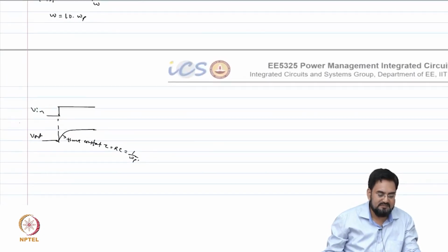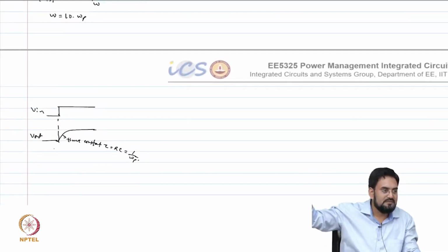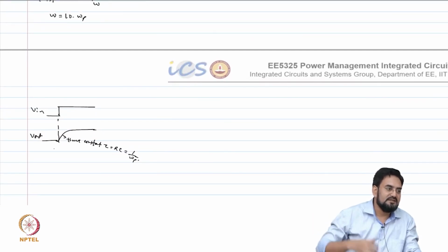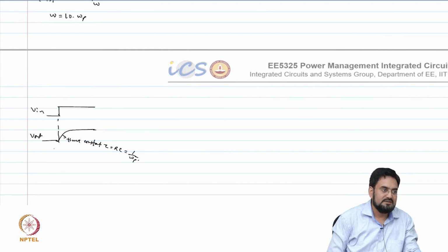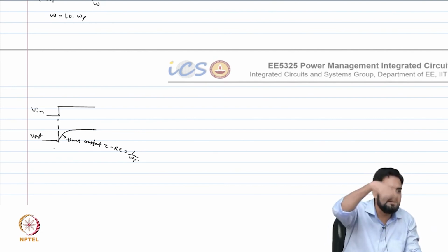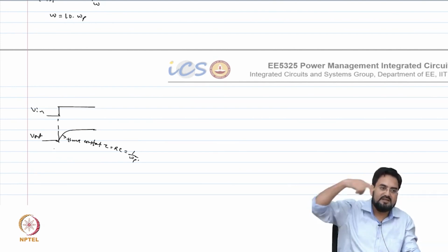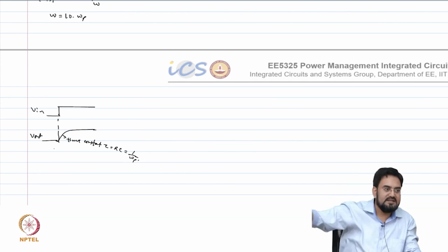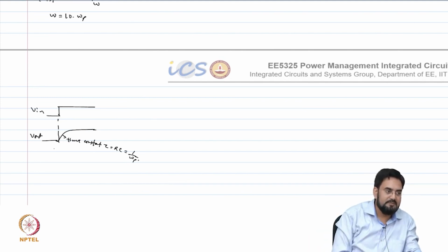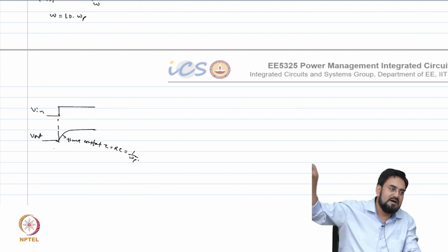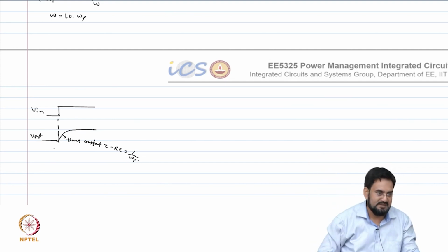This exponential term will keep increasing. This is the step response. If you look at the impulse response, it will just exponentially decay out, it will start with 1 and then go to 0. But in case of right half plane, it will be e to the power plus at instead of minus at and it will keep increasing.